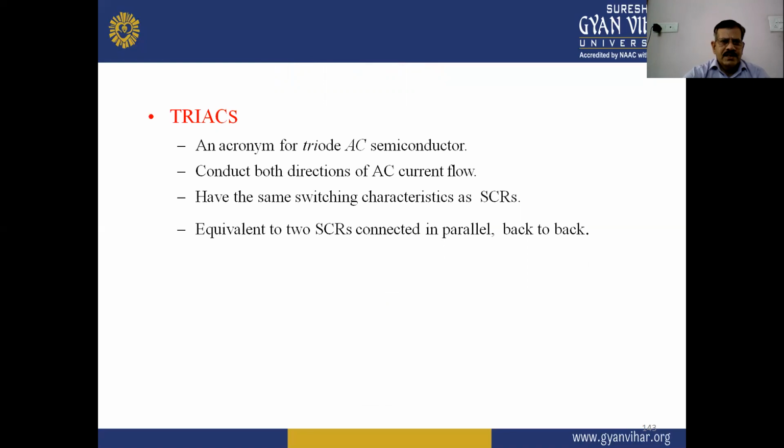So in Triacs, triac is an acronym for triode AC semiconductor. A triac conducts in both directions of AC current flow, has the same switching characteristics as an SCR, and is equivalent to SCRs connected in parallel back to back.